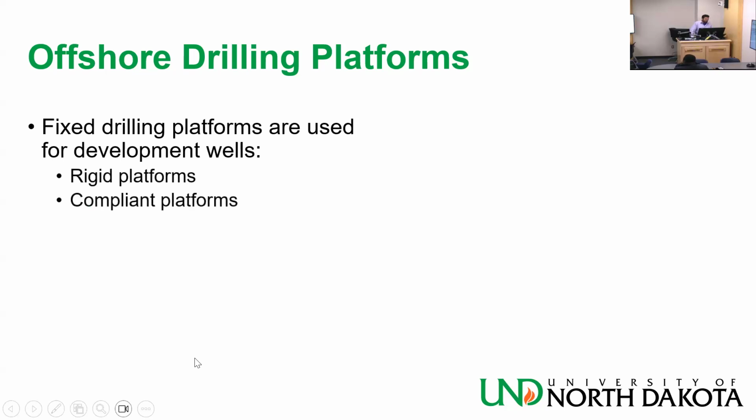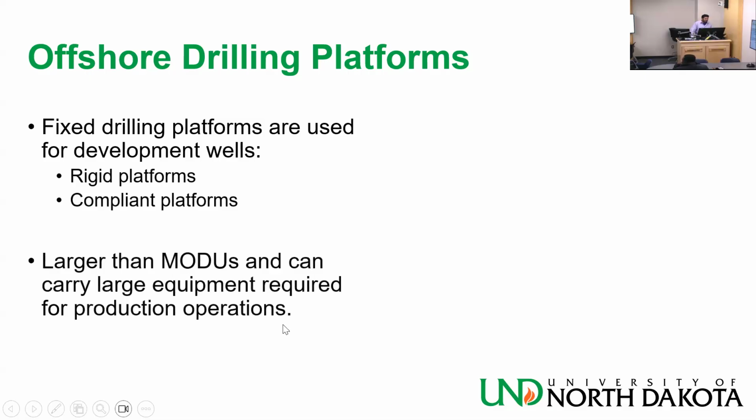Anyway, now fixed drilling platforms are used for development wells, so they are more rigid. Compliant platforms are larger than modus, and can carry large equipment required for production operations. Also, many of those fixed drilling platforms, the goal is they will drill the wells and then eventually become production platforms. So you are having them temporarily to do the drilling, and then you are going to use them as production platforms.